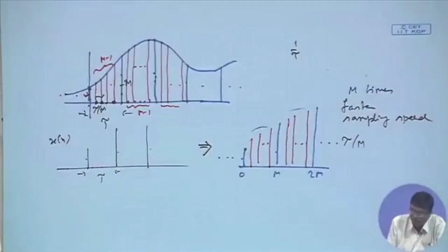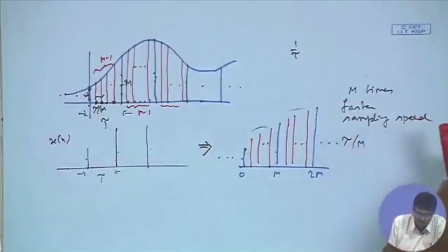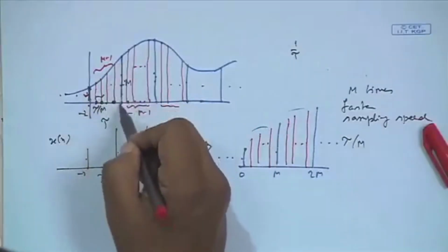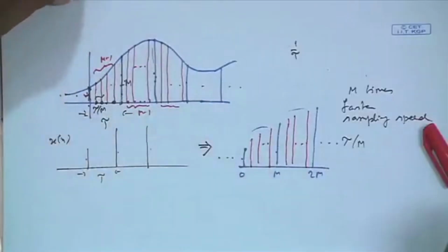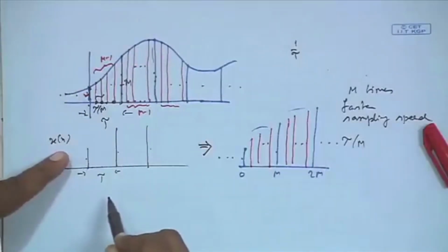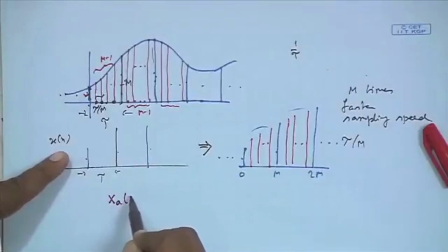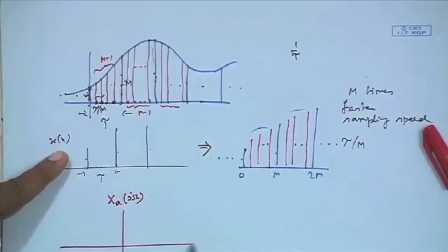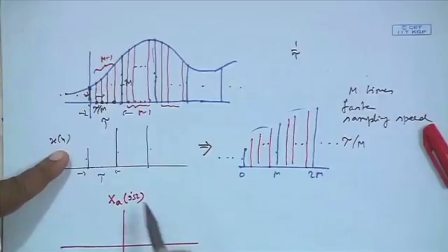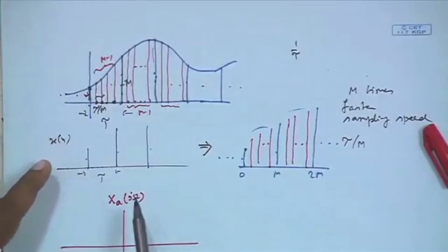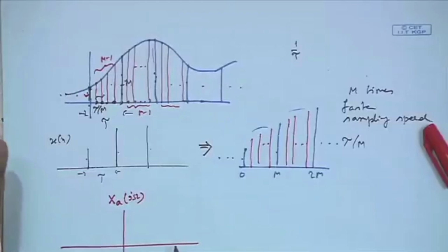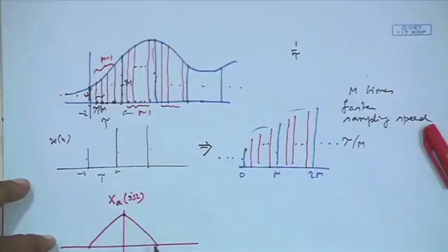So there was no aliasing originally. Therefore, if I increase the sampling rate further, there is no question of any aliasing. Now, suppose originally you have this sequence x n, and it is given that the analog Fourier transform is band limited. Again, I should draw magnitude and phase separately versus omega, because it is a complex quantity and cannot be described by one plot. But just for explaining my point, I am showing one plot only. Suppose it is something like this, a band limited function. This is your band limiting frequency, omega h.